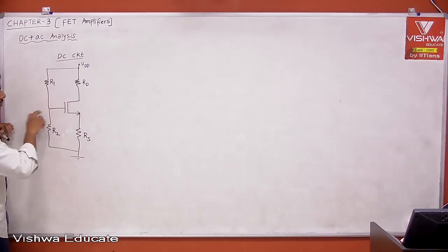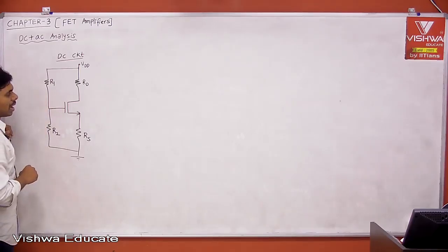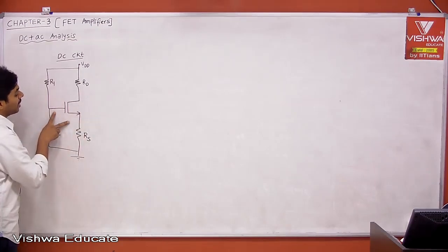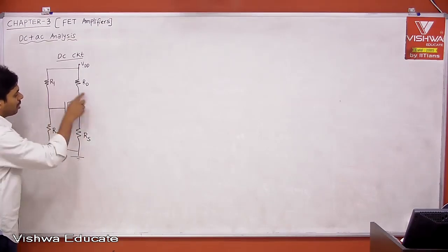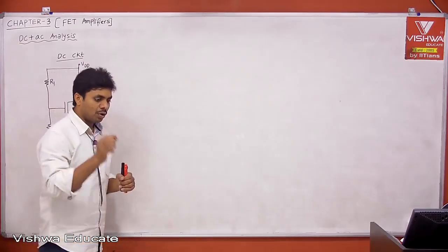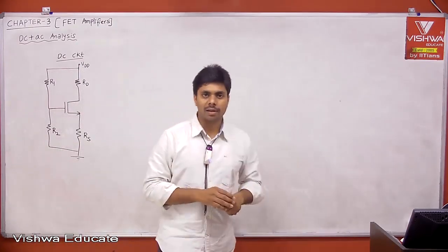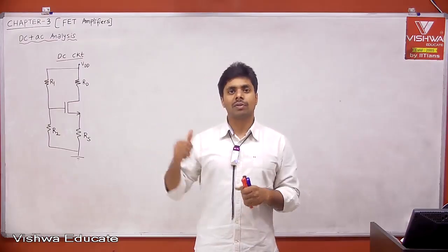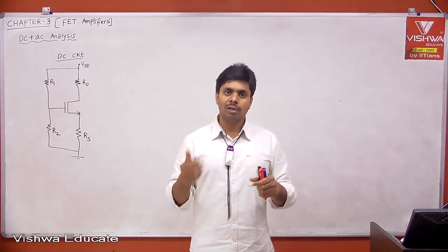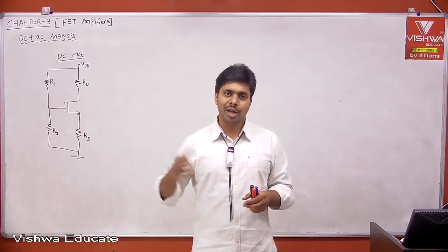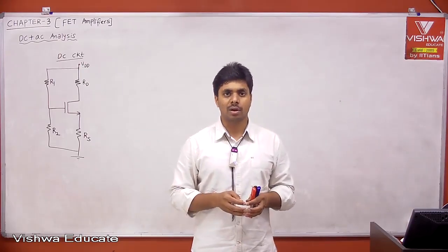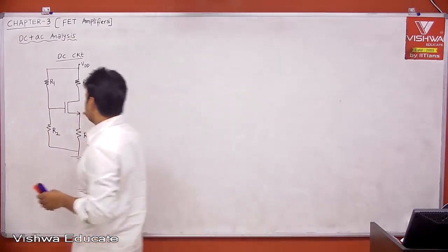Now with that VGS, right? And we know that VDS should be greater than or equal to VGS minus VT. Then only the MOSFET is in saturation. Only when the MOSFET is in saturation, that voltage controlled current source is valid. Therefore, whatever equivalent circuit we had taken till now assumed the transistor is in saturation; only then is the AC equivalent circuit valid. Therefore, this is in saturation.